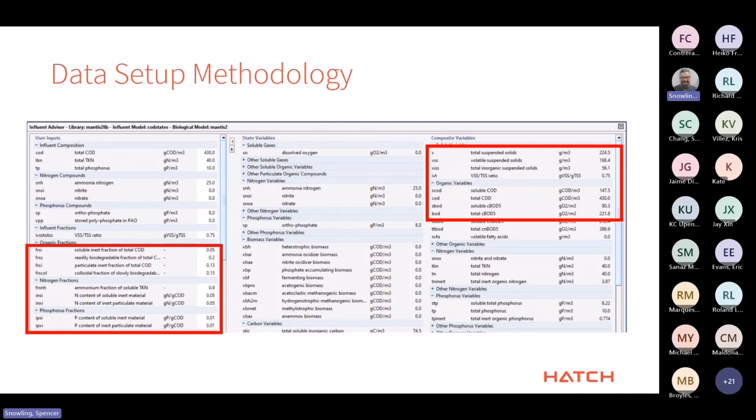One thing I always like to remind everybody is, especially if you have a lot of data, then you're probably trying to match an average over here. That average is going to be an average of a bunch of numbers that have a certain spread on them, a certain distribution, a certain plus or minus. So keep that in mind. Don't worry about trying to match it down to the nearest milligram per liter, because there was a lot more variability in your data than that to start with.